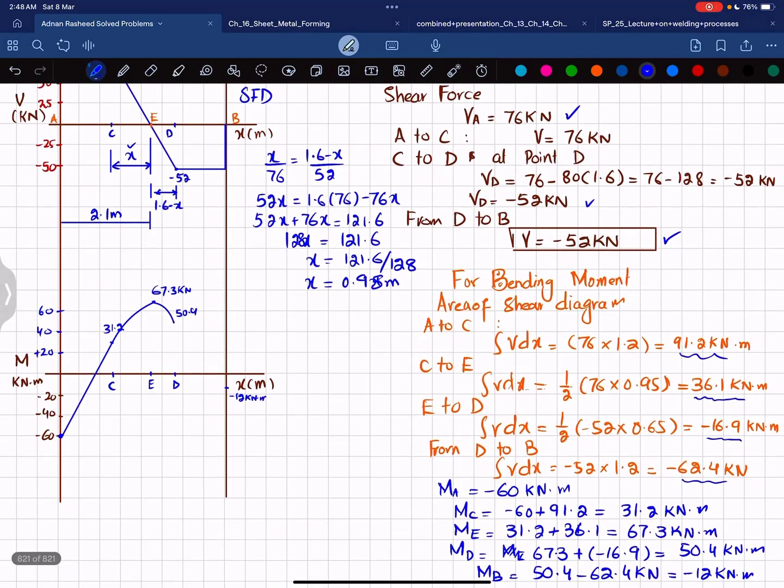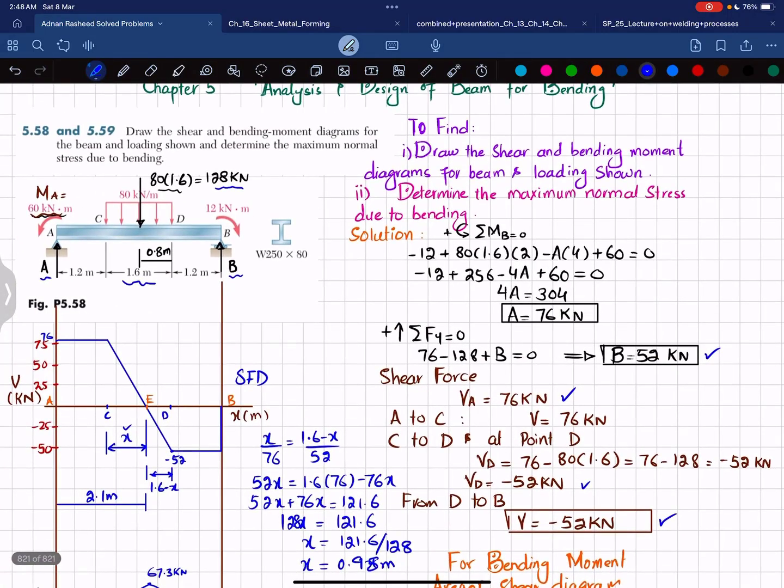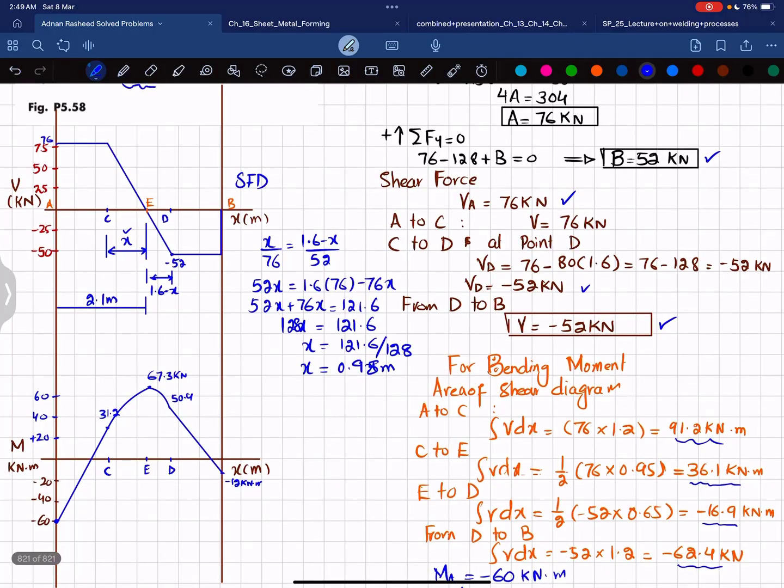And shear force is a horizontal line with 0 degree, and this area is negative. So bending moment will be one degree higher, and it will be a straight line, and slope will be decreasing. But at the end you can see you have a moment of 12 kilonewton meter, that is clockwise. So while drawing a clockwise moment on bending moment diagram, it will go upward. So minus 12 plus 12 will bring it to 0. So this will be your bending moment diagram.